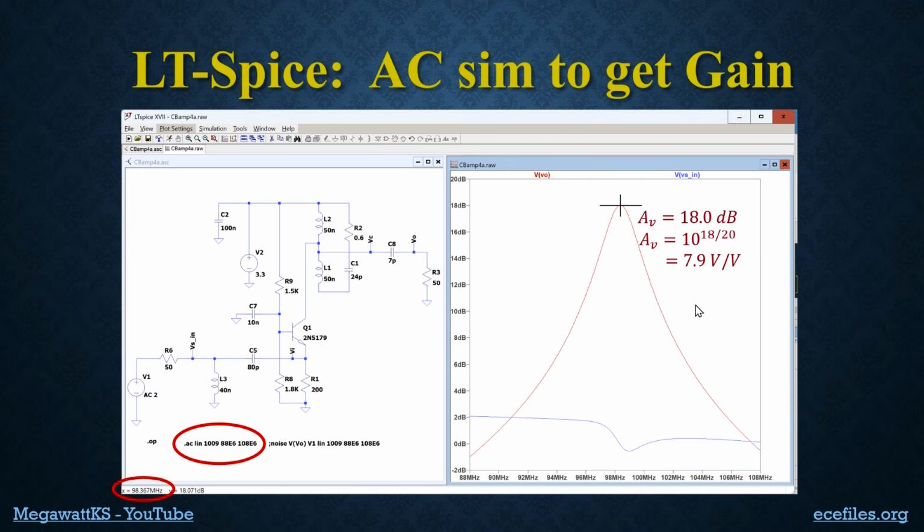And I know I may sound like I'm being sloppy, but I have built enough circuits over the years to know that there are still many simplifications that aren't even captured in the simulation here. There is, for example, inductance in this capacitor, or more precisely in the layout that runs from the ground to the base of the transistor. So this is not really AC grounded, and that's going to throw off numbers quite a bit. So this could be an error by 1 or 2 dB even when you build it.